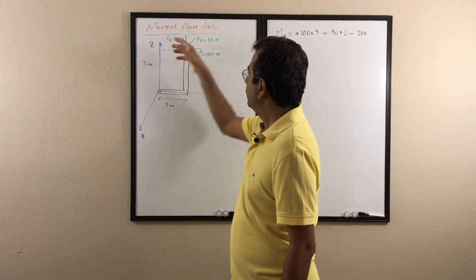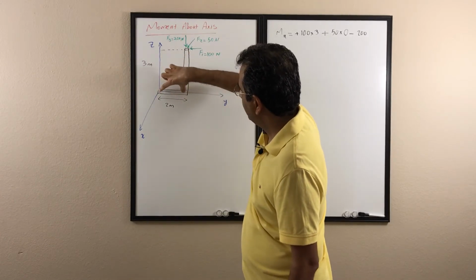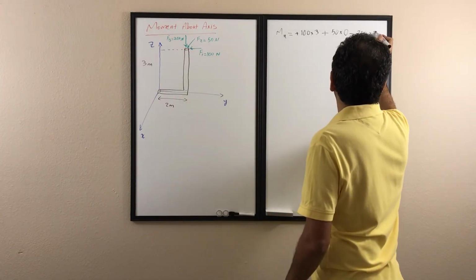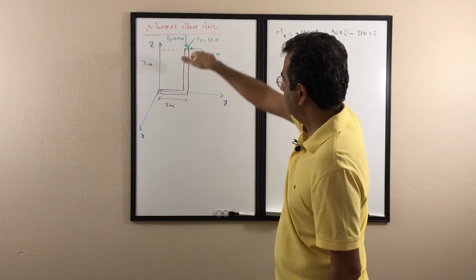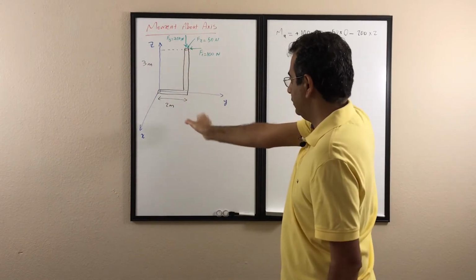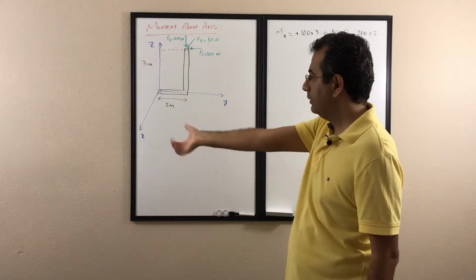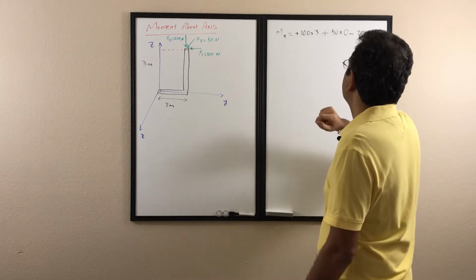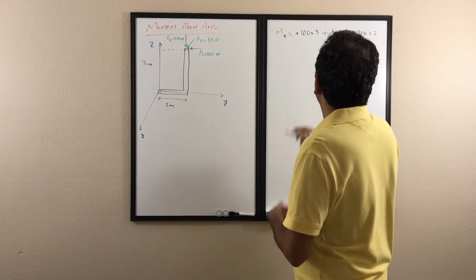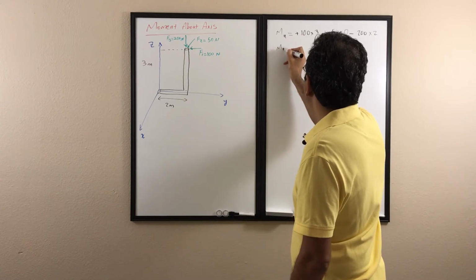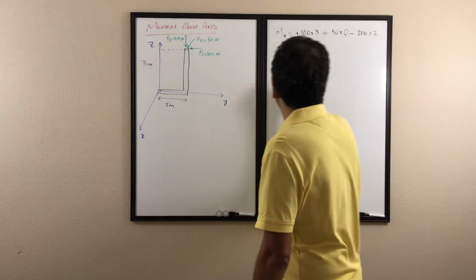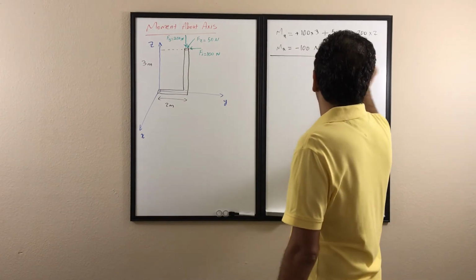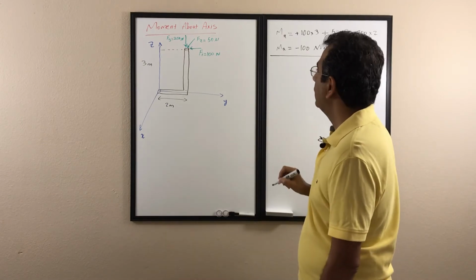And the hand of the force that's rotated, if I extend that, and the normal distance between that and the x is 2 meters. So that's 2 meters. Its direction, so it's rotating it like that. So it wants to rotate it like that. If I put my forefinger in the rotation, my thumb is going to be in the negative direction of x. So it's going to be negative. So my M about point x is going to be negative 100 Newton meter. So that's the moment about axis x.